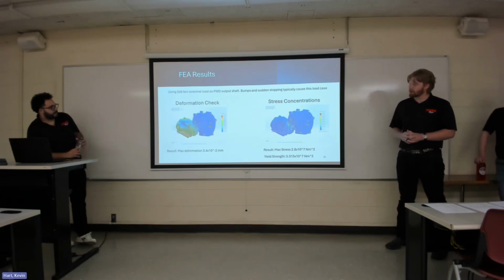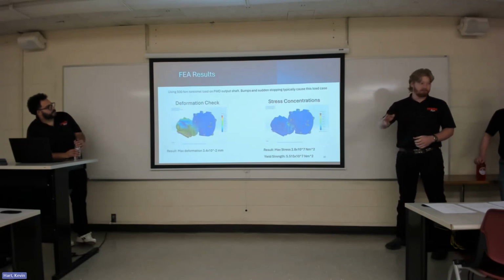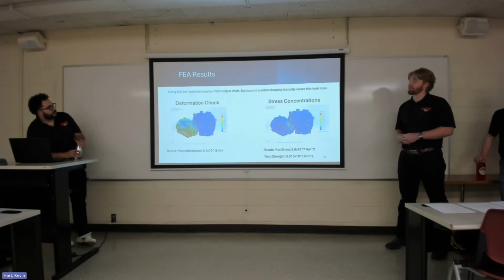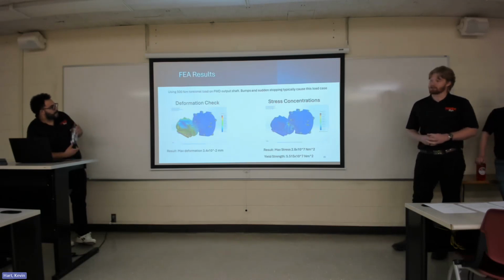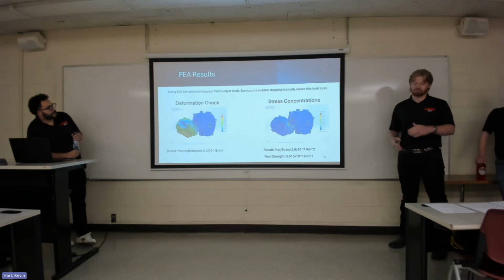I did a torsional load on the front wheel drive forward section. A lot of teams we've seen run into something and then their whole side of the case will just come off. So we wanted to make sure this would actually survive an impact like that. And this is really common if you're going up. They'll set up like the concrete road barriers and tell us to drive up them.